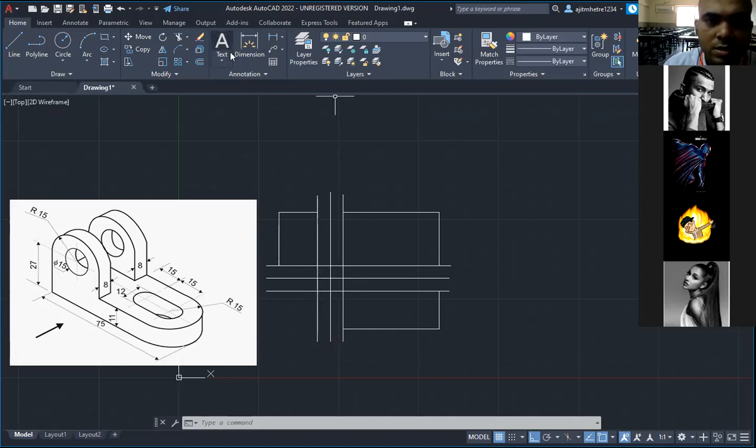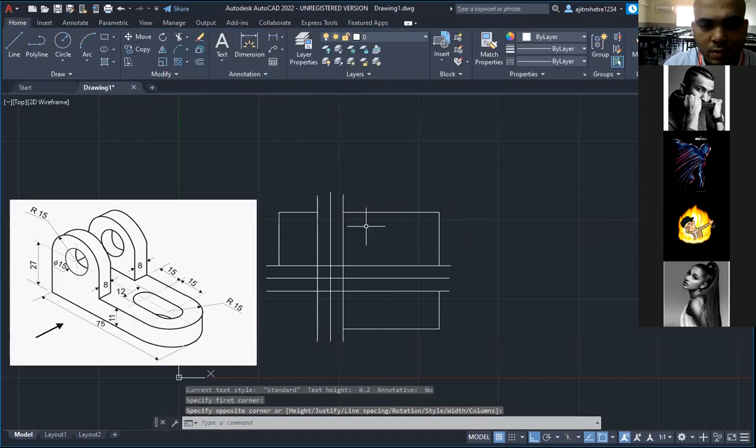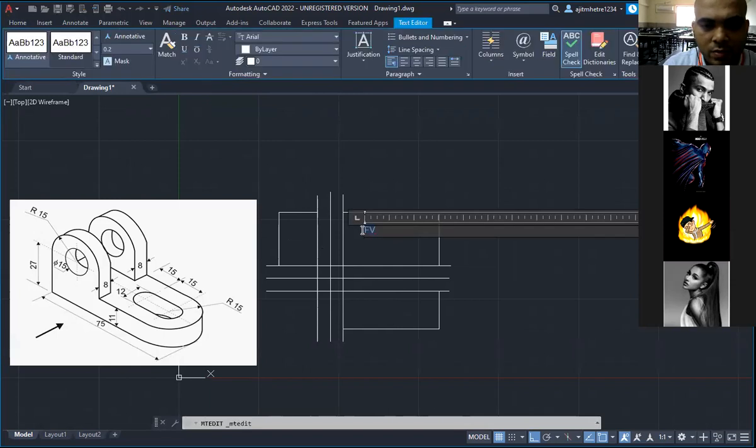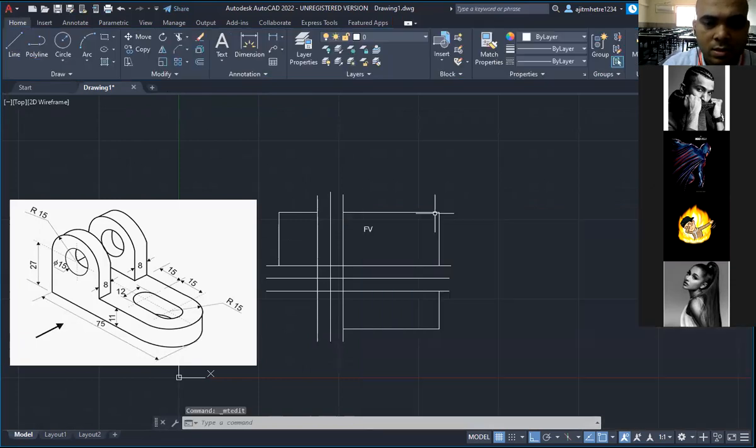After then, this is very important. Which view comes from where? Okay. As I told you already, the front view will always be above the XY line, and after that we will have the top view. The top view will always be below the XY line, and the side view you have to keep in mind.